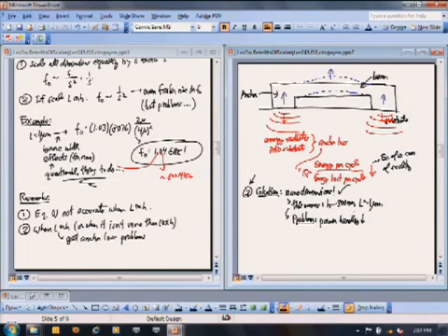It could be a mile away. Whereas your buddy is sitting there with his or her cell phone and transmitting right there 2 feet away from you. Okay, so your phone has to reject that transmission 2 feet away from you, which is going to be maybe 80 dB stronger than the signal you're trying to pick up. That 80 dB signal hitting your antenna and then hitting this tiny nano mechanical device, I don't know if it'll blow it out, but it'll create nonlinearities that will corrupt your whole ability to receive the faraway signal.